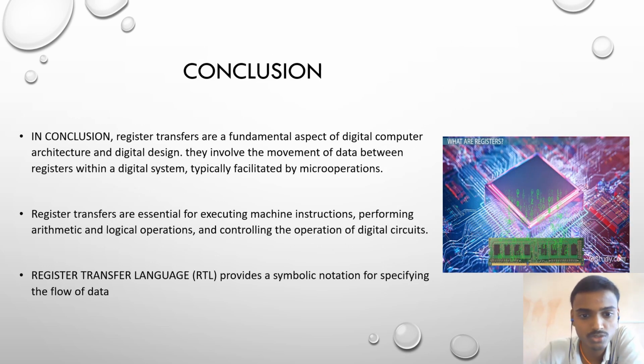Let us see the conclusion of what we have seen till now. In conclusion, register transfers are fundamental aspects of digital computer architecture and digital design. They involve the movement of data between registers within a digital system, typically facilitated by micro operations. Basically, register transfer is transferring the data from one register to another register and performing certain micro operations between those two registers and storing the result into another register or within the same register. Register transfer is essential for executing machine instructions, performing arithmetic and logical operations, and controlling operations in digital